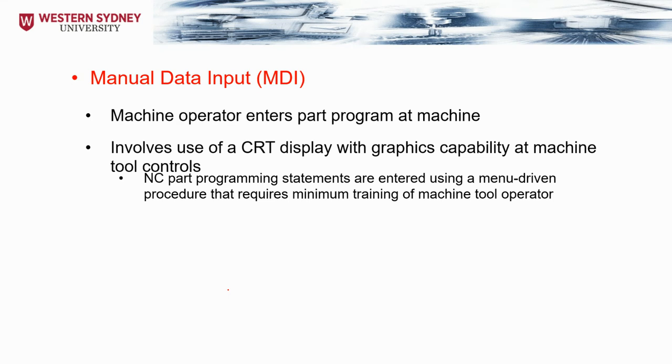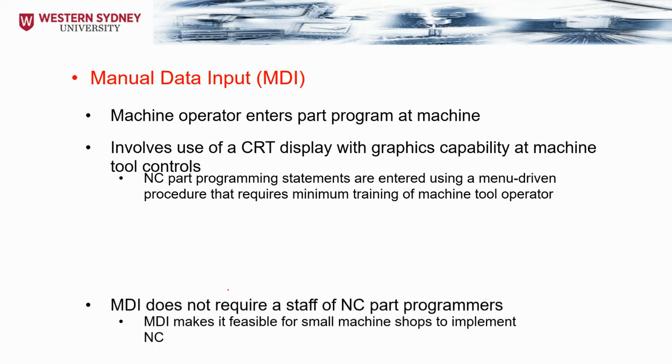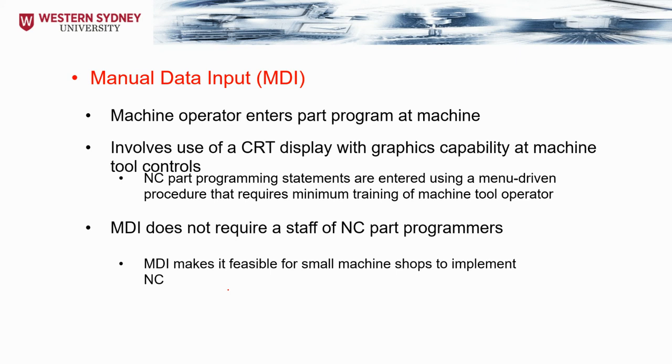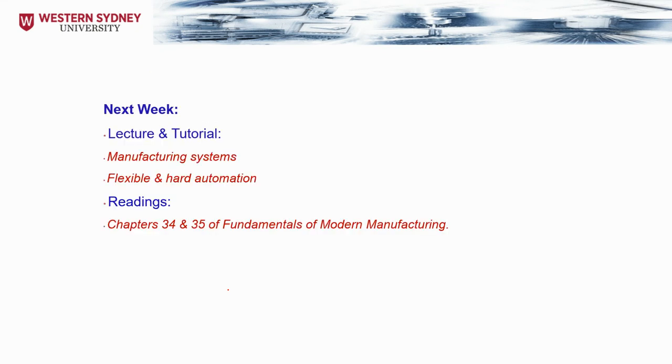So in that case, the numerical control part programming statements are going to be entered using a menu-driven procedure that requires minimum training of the machine tool operator. The MDI does not require a staff of numerical control part programmers. So the MDI makes it feasible for the small machine shop to implement the numerical control system.